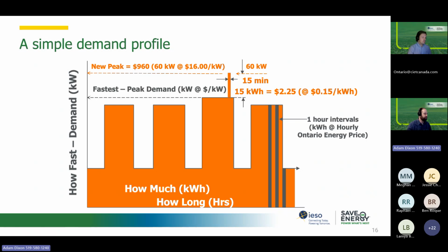So someone turned on a heater, and again, maybe they needed it, but it did happen to set their peak demand. If you are on a demand billing rate tariff structure, you do have to consider when you turn certain electrical loads on in order to avoid setting your peak demand. But one way to prevent this is to take a look at the base load in your building. If you can pull energy out of your base load, it will bring down the entire profile, and even if you do set a new peak, it's not going to be as high as it once was.